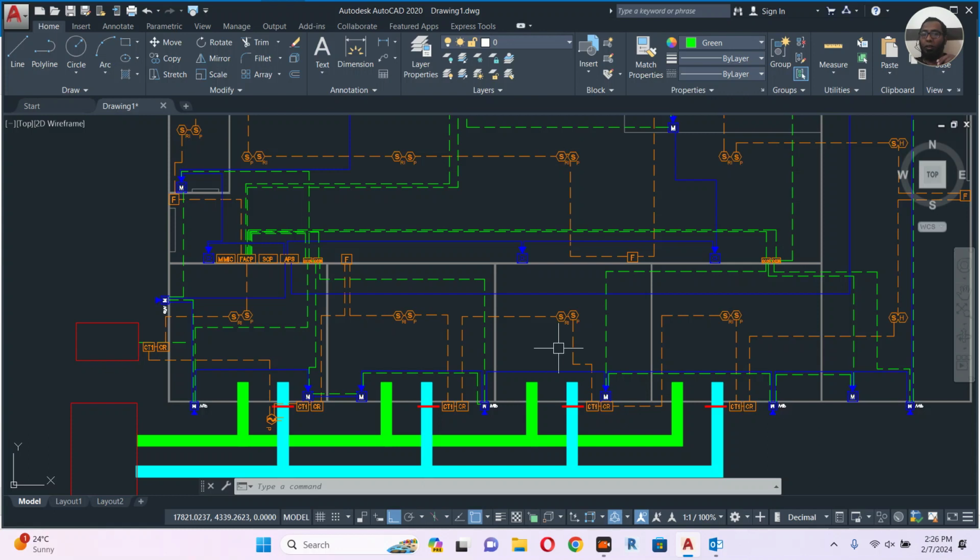In case of fire, the fire alarm control panel will give an order to the control relay. It will trigger the access control panel to make all the doors open. Whatever connection inside the panel between the control relay module and the access panel, the specialist will do.